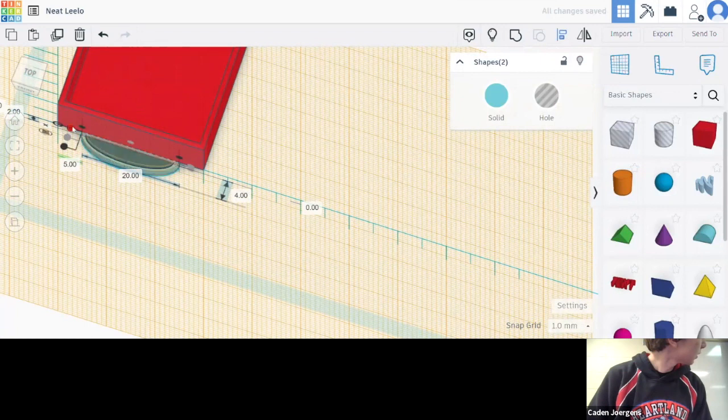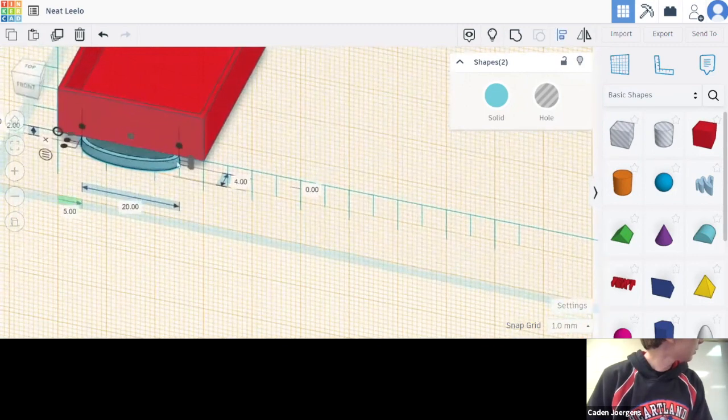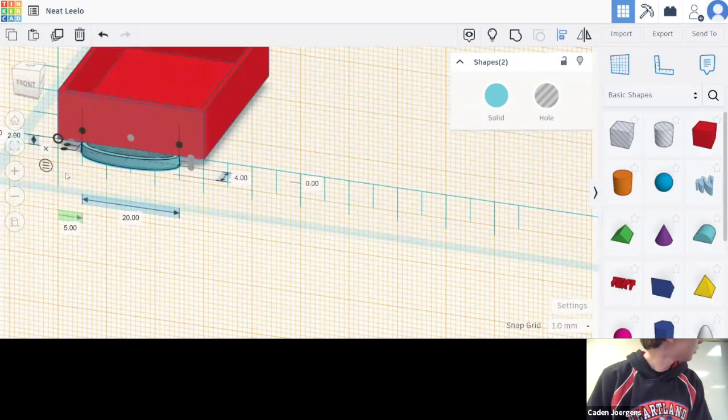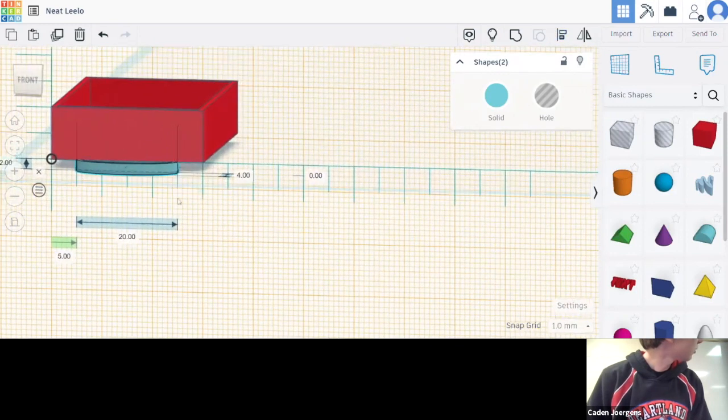Actually, I want this aligned on the back. Yeah, that makes sense for a handle. So here we had it aligned really high up, but then we also had it on the middle x-axis, but we could just have it hit the back of its handle's x-axis, which is a little bit easier. And then we have it aligned on the middle y. Let's see here. Can I align it on the middle z? It should already be aligned on the middle z. So it is grayed out.